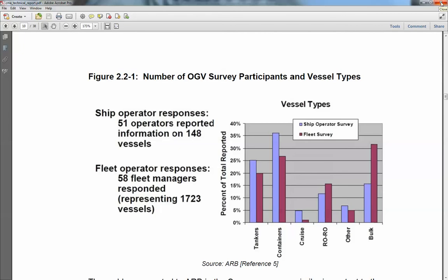Typically the students have a problem with this: they don't understand the difference in these fuels. This is not gasoline. You just don't put gas in the tank and drive away. Some of the heavy residual fuels that you're burning on the ships today go to an absolute, rock solid at room temperature. So if you don't understand your fuels, you're not going to get very far.